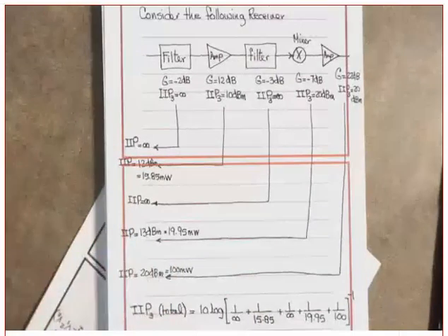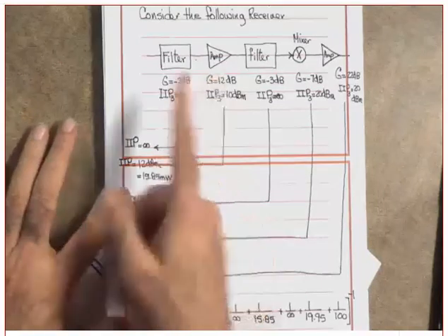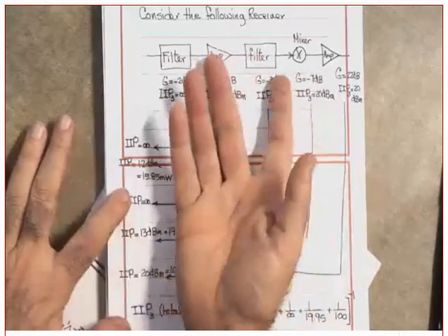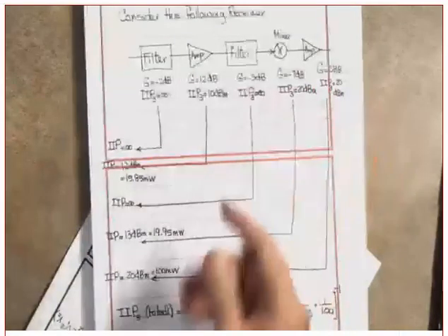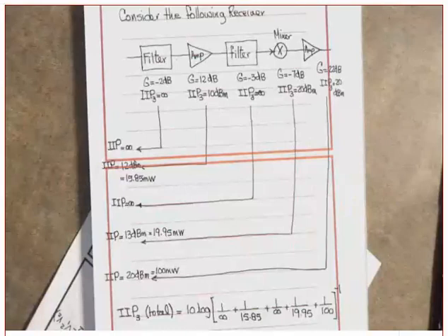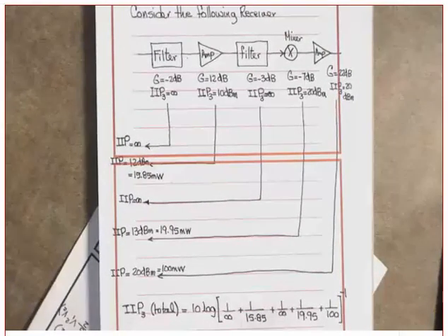Yes or no? When we get to the noise figure, I will show you that the overall noise figure is dominated by the noise figure of the first block. Are you following me or not? By the way, was the amplifier the first block here? It was not the first block. But in the noise figure, no matter how much gain you have, the influence will be the one that is the first block in the chain of your receiver. And hence, we need to use some amplifier which introduces little noise. Little noise. The low noise amplifier that has the smallest noise figure.